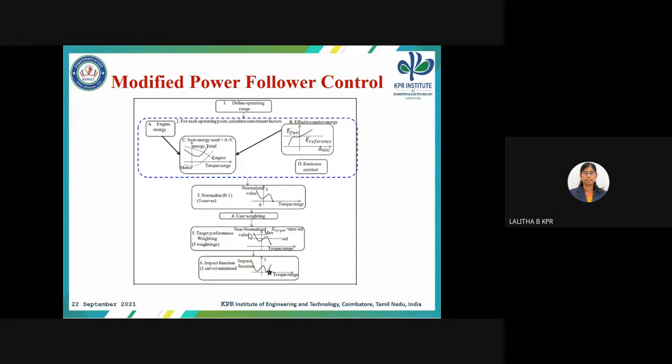The greatest possible positive motor torque defines one extreme of the operating point range. This value is the minimum of three values. The first one, the driver torque request. The second one, the maximum rated positive torque of the motor at the current speed. The third one, the maximum available positive torque from the electric motor according to the limits imposed by the capability of the batteries.